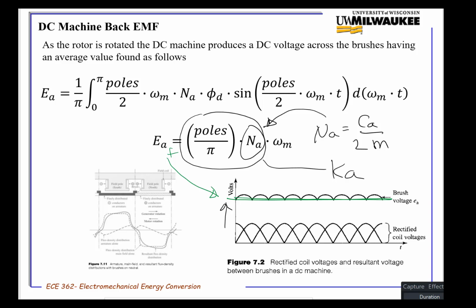For the interested person, the armature effect that we were talking about, as you draw more current, only changes it a little bit by putting a little dip, a little tilt in the shape. And we pretty much ignore that impact on everything. It doesn't really change this level of voltage.